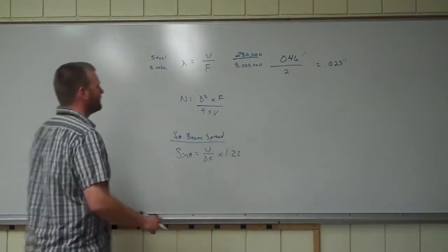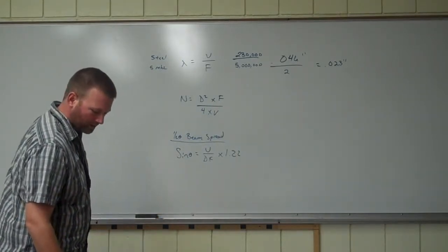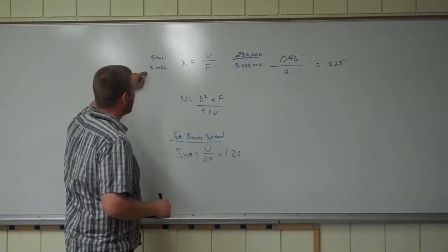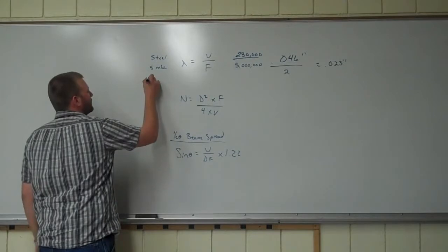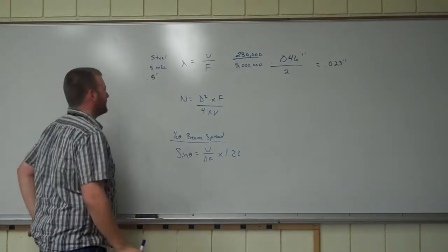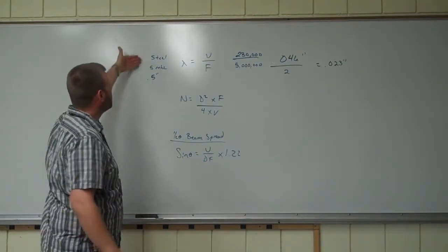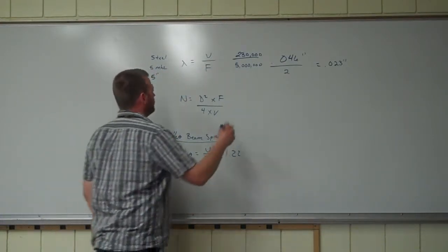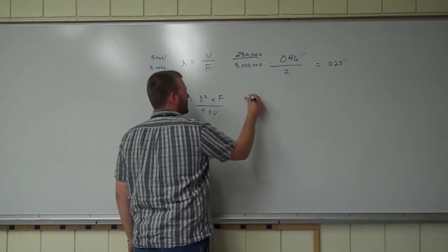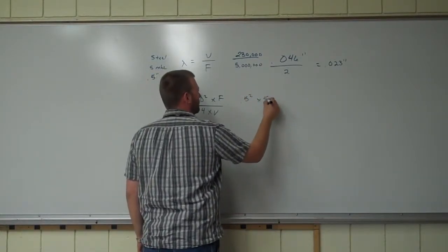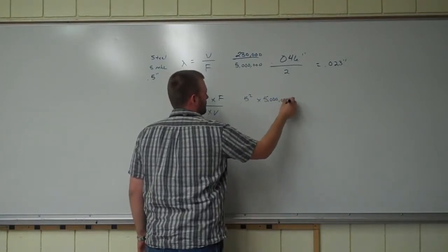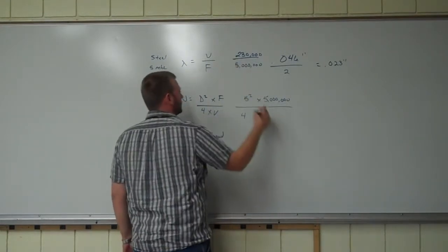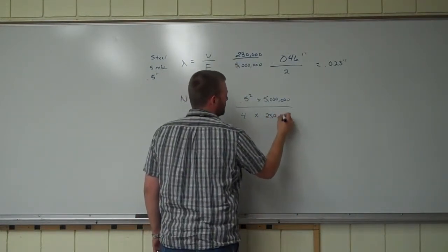Relatively simple. The next one, near field, is along that same line. We're going to stick with these same numbers: steel, 5 megahertz, and we need a diameter of the transducer, so let's make it easy, let's say it's 1/2 inch. We're just going to take these numbers and plug them into this formula. It's really not that bad. So 0.5 squared times frequency over 4 times velocity, that same velocity, 230,000.